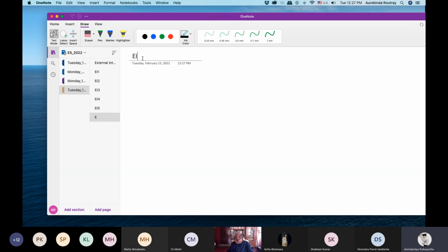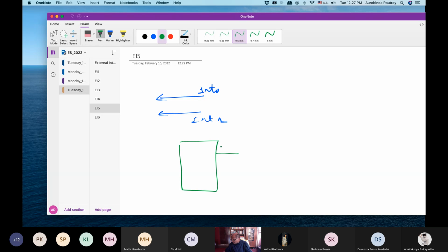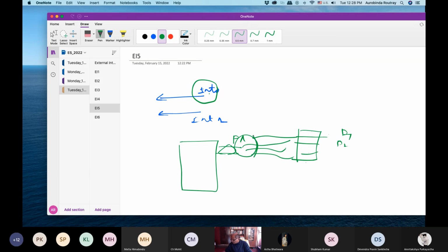Sir, how will we connect them to the flags? So the Atmega has certain ports like port B, port C, port A. So you can connect 4 pins of the port to the devices. So this will set these pins. Suppose device 1 is here, device 2 is here. They are also connected to the interrupt through the OR gate. So whenever INT0 fires, it will check this port. Whichever is enabled, it will serve that ISR. You got it? Are you getting it? Yes.